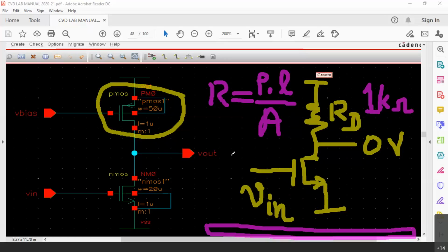But power transistors are not possible even inside the chip. If a large amount of current or power has to be handled by a transistor, we cannot integrate it as a silicon chip in VLSI. We will have to have a larger transistor only. That's why you could have seen in the labs, the power transistor mounted behind the power supplies.